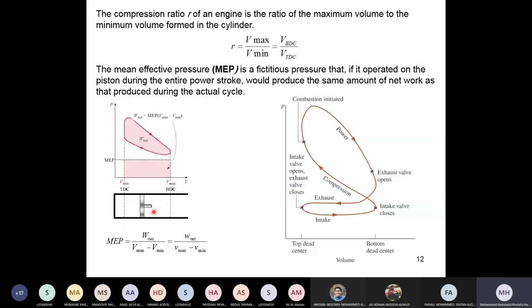So when you read 3.5, it means that the engine you have, the volume of one cylinder multiplied by the number of cylinders, will give you this. This is the volume there. It's not the total volume. It's not the clearance volume. It is the volume between this point and this point. This is what we call the swept volume, and this is what's given in the car, and this will present how much power this car has.